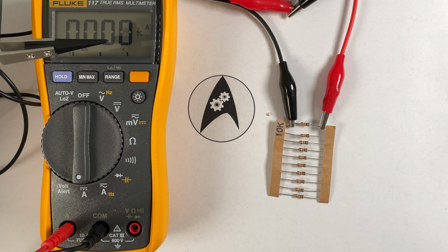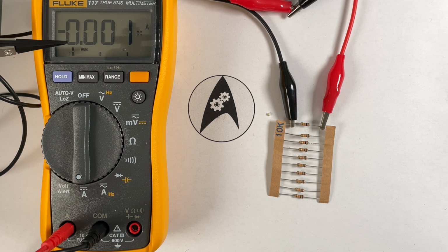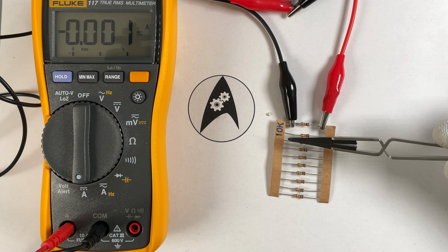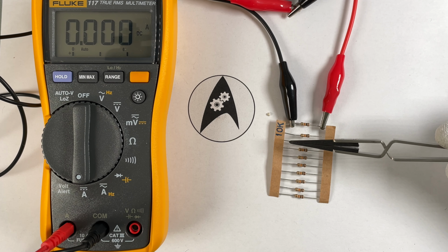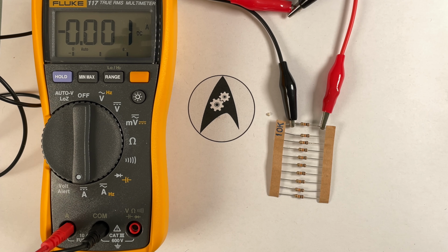And as you can see here, we are observing no current flow at all. We have a small disturbance here in the third digit, but apart from that, there's absolutely no indication that any current is flowing here. And the problem is that we are really using a very high resistance value here. We have a 10 kilo ohm resistor and we only have a 5 volt power source. So basically we can do two things. We can increase the voltage. Let's do this just for the sake of completing this first phase of the experiment. Let's set the voltage source to, let's say, 20 volts.